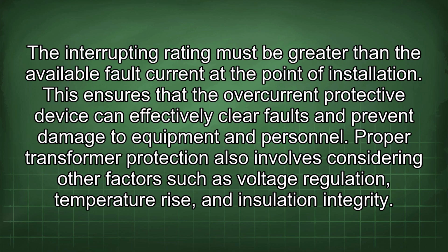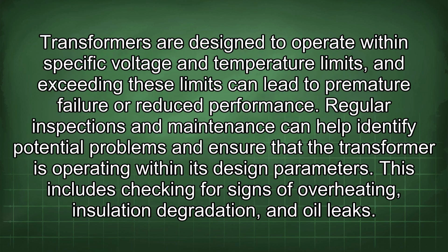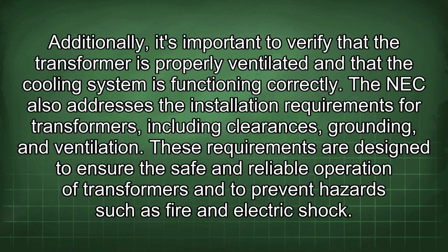Proper transformer protection also involves considering other factors such as voltage regulation, temperature rise, and insulation integrity. Transformers are designed to operate within specific voltage and temperature limits, and exceeding these limits can lead to premature failure or reduced performance. Regular inspections and maintenance can help identify potential problems and ensure that the transformer is operating within its design parameters. This includes checking for signs of overheating, insulation degradation, and oil leaks. Additionally, it's important to verify that the transformer is properly ventilated and that the cooling system is functioning correctly.